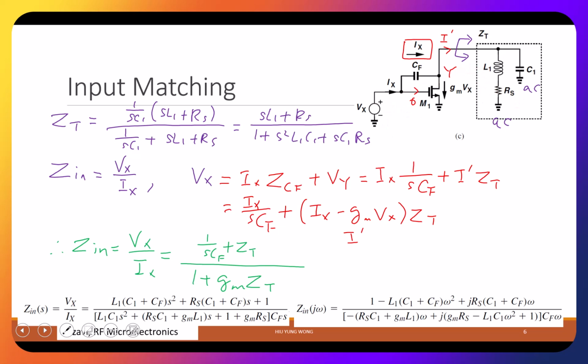Now, when you do RF, you need to go through a lot of this type of calculation. Pretty troublesome. It's easy to make mistakes. But you train yourself. We don't test this in the exam, of course. Don't worry, I'm not going to ask. But you need to first train yourself the skill so you know some pattern. Second is you can program this in Mathematica or whatever when you really design your circuit and put the equation in Excel. Then you try different quantity, different frequency. Then you can get the impedance you want. This is actually also a part of your project when you design your low noise amplifier.